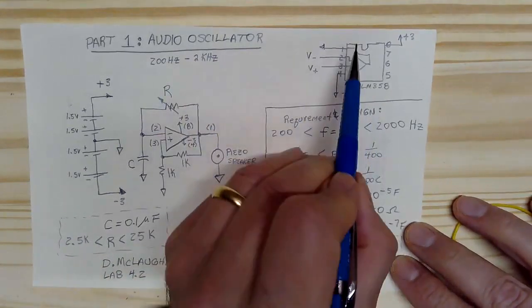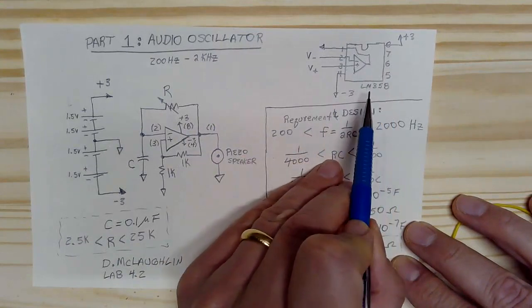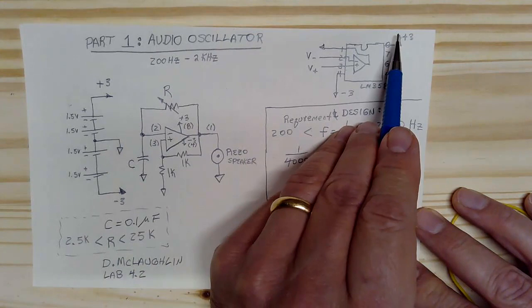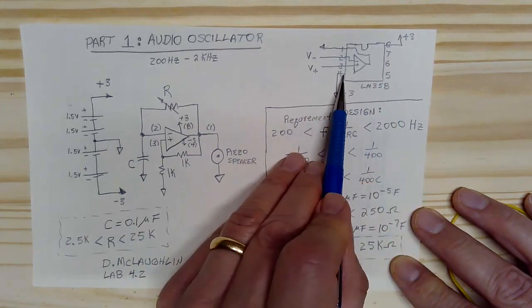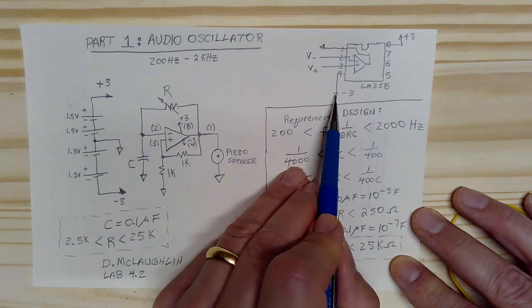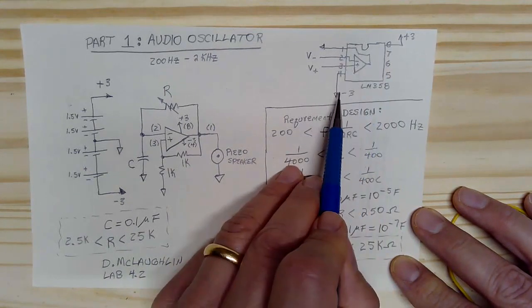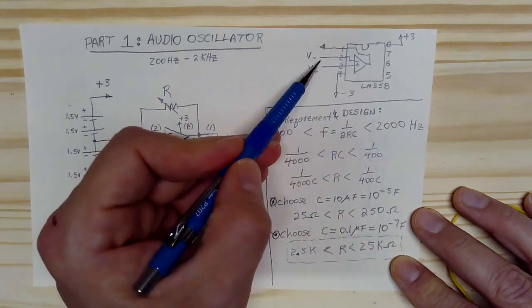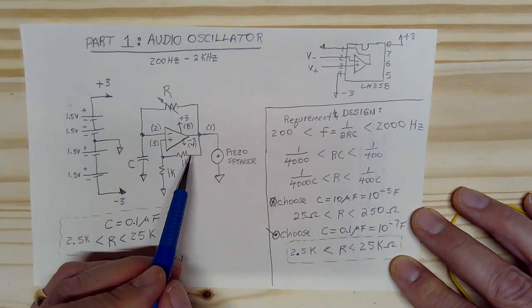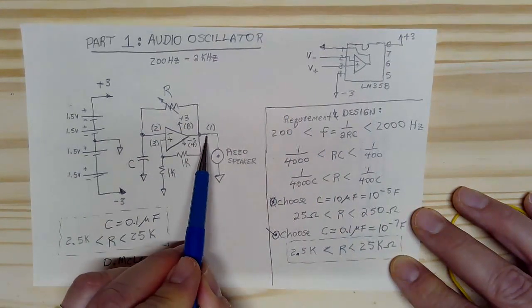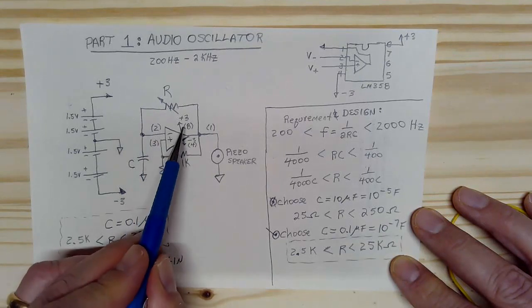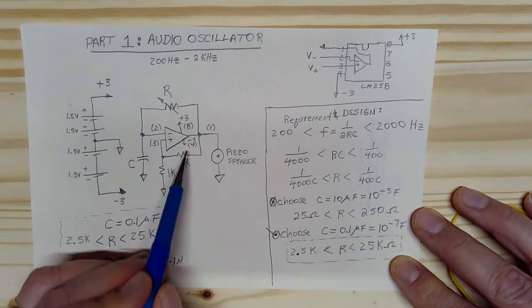And so this is the pinout of the op amp chip that we'll be using for both oscillators. We have VCC is +3, and then instead of ground, which you've grounded in previous experiments and labs, we'll be connecting that to -3 volts. So that powers up the chip. And then we have our inputs on pins 2 and 3 and our output on pin 1. And so I've just shown over here, we have the output on pin 1 and the inputs on pins 2 and 3, and then the power supply is on 8 and 4.